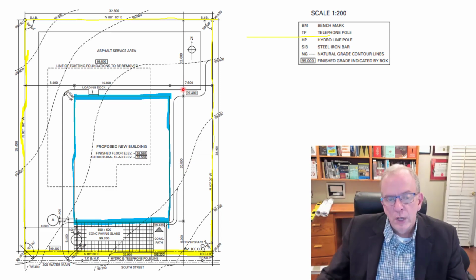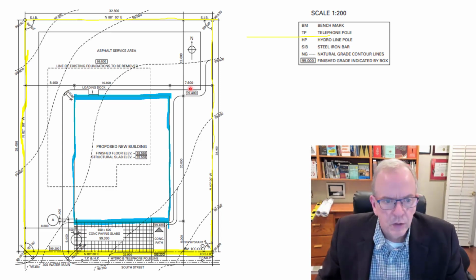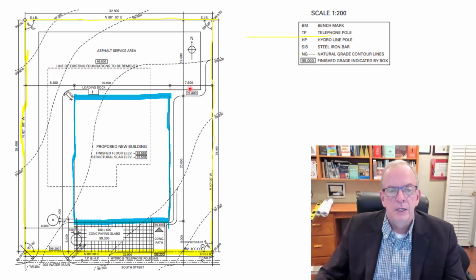In metric, you just move the decimal place 3 places. One for decimeters, centimeters, millimeters, right? That's the nice thing about metric. So all you've got to know is, if I'm dealing with meters, I move it 3 places, and then I'm into millimeters. Most construction drawings, if they're in metric, will measure out in millimeters.